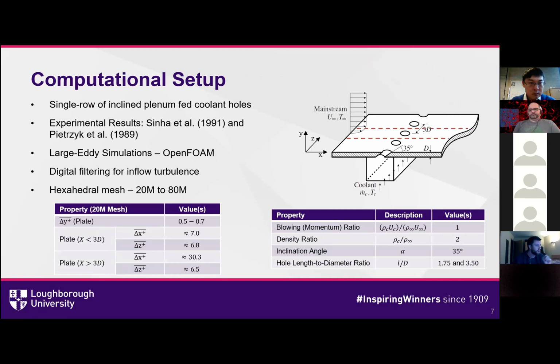These simulations have been conducted with OpenFOAM, which is a little different to some of the work shown in these previous presentations. But for us, it provides a suitable platform to implement these data-driven methods in a very simple manner and extend upon them. Also, because it's an unstructured solver with some links to industry, we're able to address further geometric complexity when assessing things like turbine arrangements and combustor flows as well.